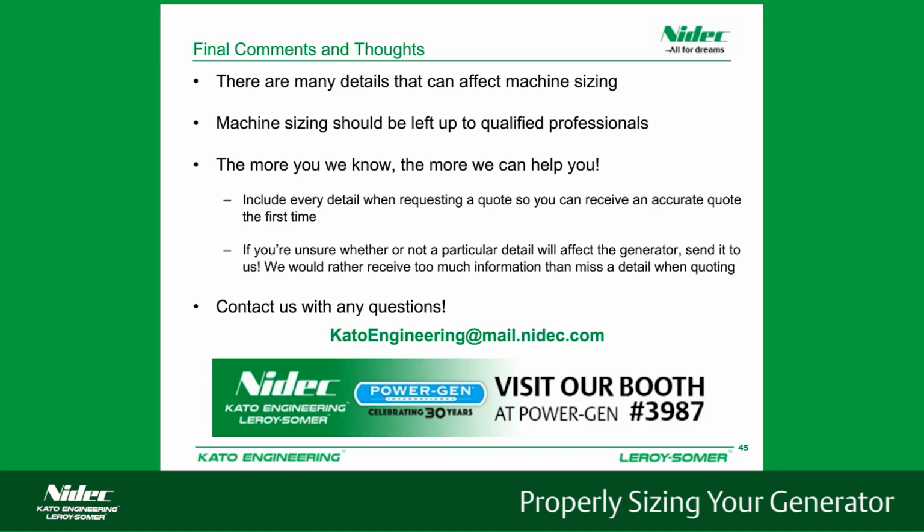That's great, thank you. Okay, and the last question we have today is, what controls the power factor? Is it affected by the generator? Well, I guess you could say it's slightly affected by the generator, because the generator does have a little bit of an inductive component to it, but it's very, very small compared to the load that you're connecting to.